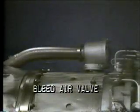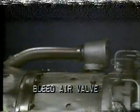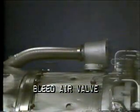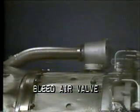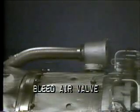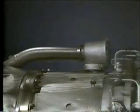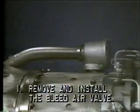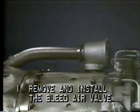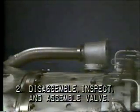The bleed air valve should receive routine maintenance at the first 1,000-hour interval and at each additional 4,000-hour interval. This maintenance should include removing, cleaning, and inspecting the valve. When you finish this lesson, demonstrate your understanding of the material by taking the performance check on the following performance objectives. First, correctly remove and install the bleed air valve. Second, disassemble, inspect, and assemble the bleed air valve.